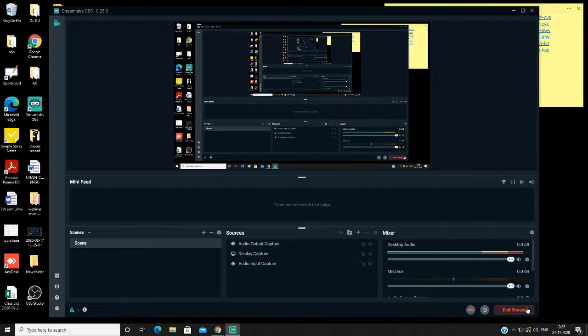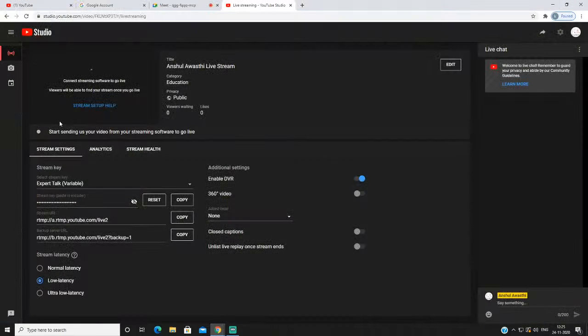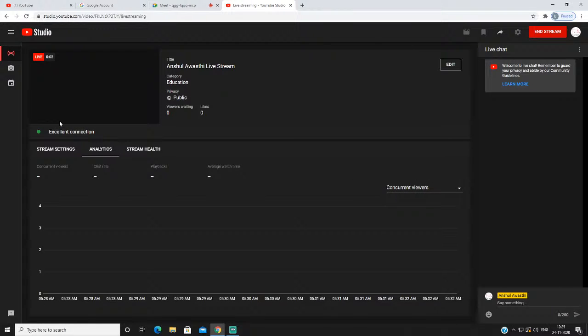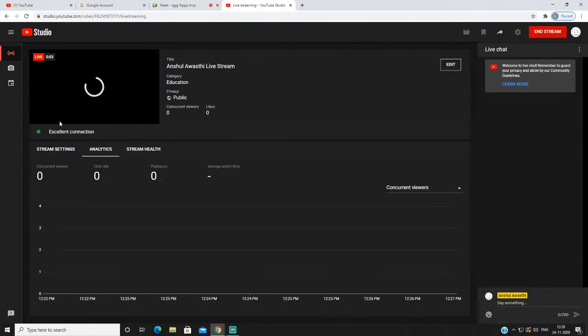And that's why we use the reference electrode. So what we are doing, we are simply converting hydrogen ion concentration into some potential, and then this potential is being measured with respect to some reference electrode. So you simply converted your concentration into some potential, and you draw a calibration curve and you make your pH meter.